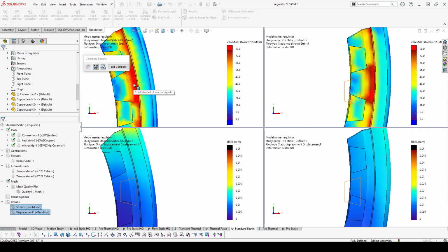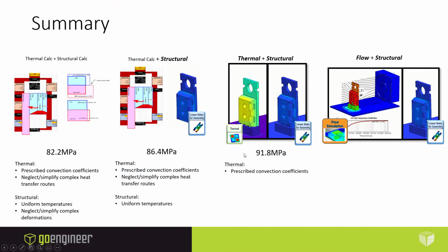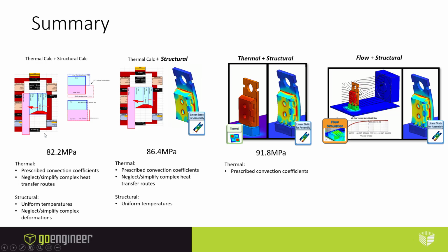And then the stress levels, they look about the same, but if I look at you can kind of tell that this one spreads out a little thicker, that one's a little more, and it could just be a mesh thing. But really, the key thing to look at was that sensor that I had probing that surface for comparisons. So when I ran it just now, we got a result right around this 91.8. It was even bigger than the last one. Even with the conservative assumptions I tried to make with the hand calculation, I guess it wasn't conservative enough.